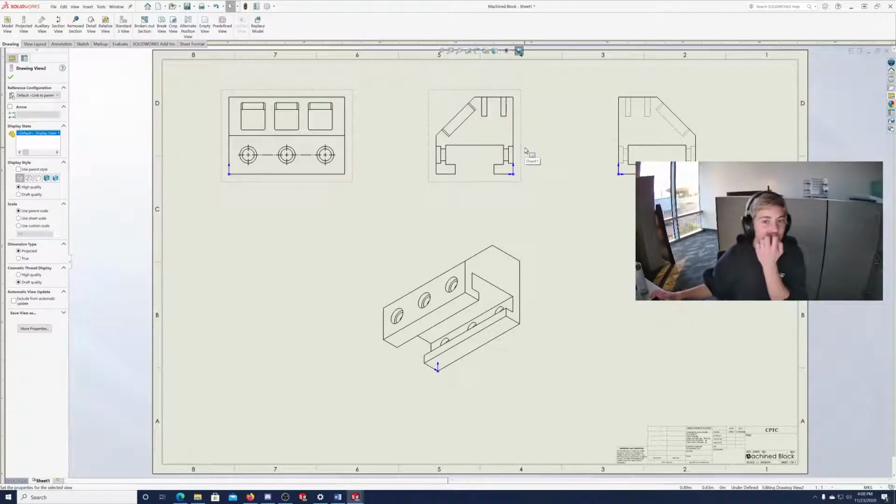So this is kind of confusing a lot of the time on a real mechanical drawing. You don't really want to use this because somebody looking at the drawing isn't going to know that these lines are inside the part. They look like they're on it. You can't really tell what's going on. You're like, what are these? For instance, these holes on top, are those grooves, or are those holes inside the part, or are those like raised ridges there? You can't tell. So that's why hidden lines visible is cool, is because they're dotted, so you know those are inside the part.